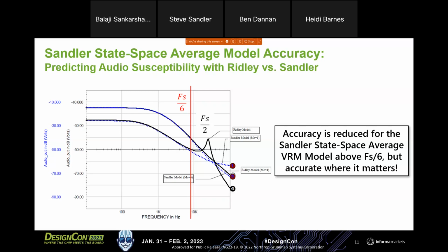The answer was really simple, actually. Picture this simulation that's running and the output current is very low. So the power supply is sitting there in discontinuous conduction mode, and we do this load step, and all of a sudden it crosses the discontinuous-continuous conduction boundary. And what are we supposed to do with that? Are we supposed to say, whoa, stop, wait, we need to switch models here? No, we actually needed to be able to run through it.